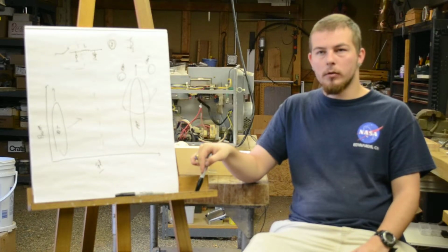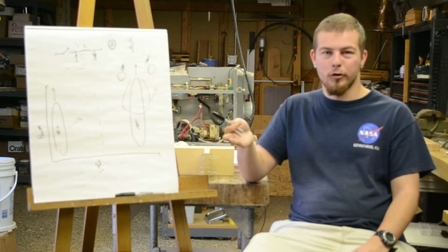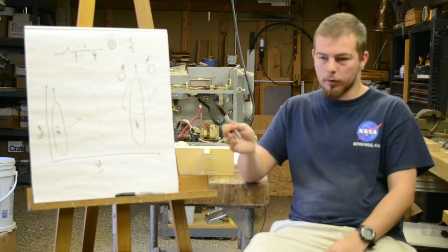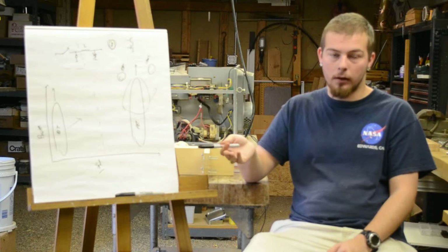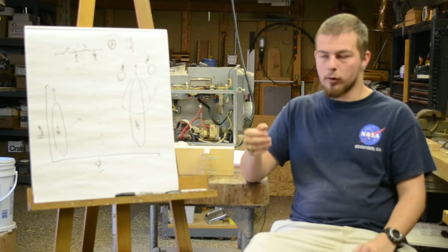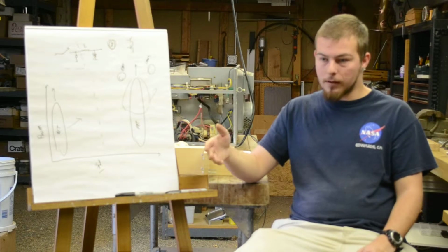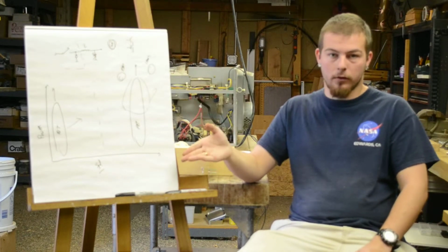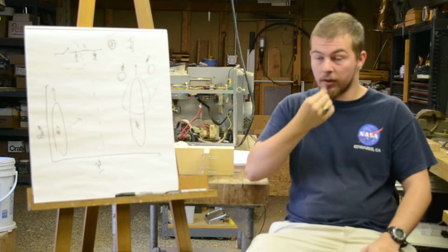The only problem is that, first of all, it's extremely inefficient, because you have to convert one voltage into AC, then jam it through a transformer, which is inherently lossy. Obviously nothing can perform like an ideal transformer. Then you have to induce losses in the rectification diodes to convert right back to DC, and then you have to filter and reduce ripple and everything.